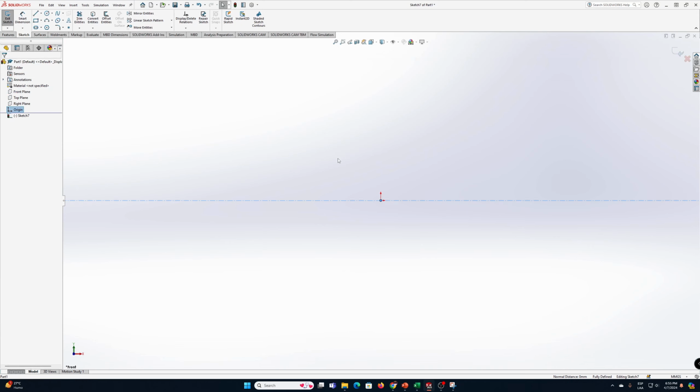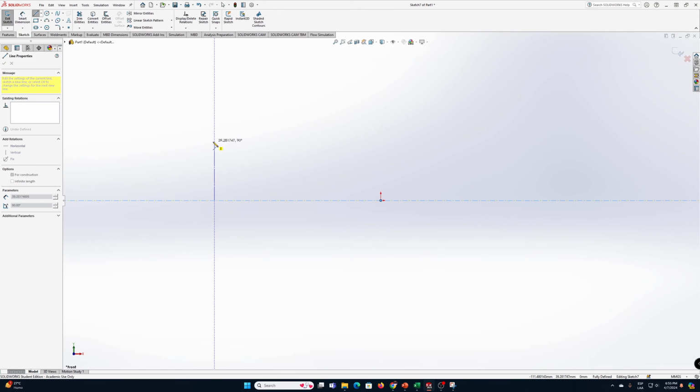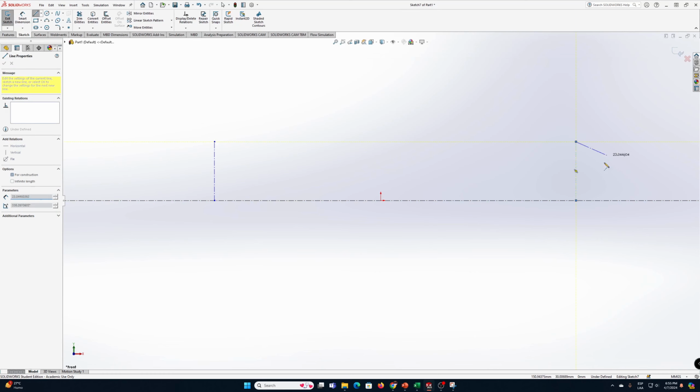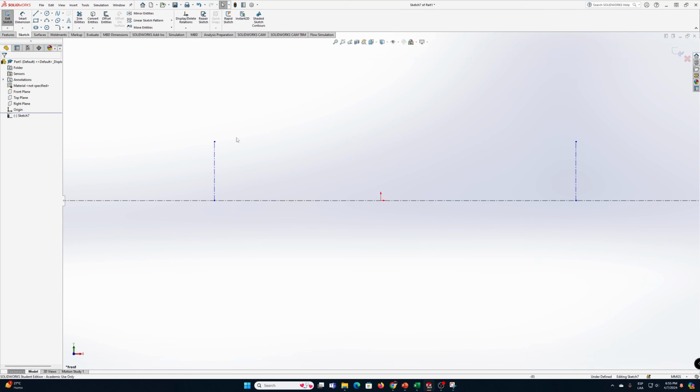And okay again. Now that we have selected that option, the only thing we need to do is go again to center line and create a construction line like this one. I will put it here, another to this point. Don't worry about the dimension because we will use the smart dimension option to modify it.